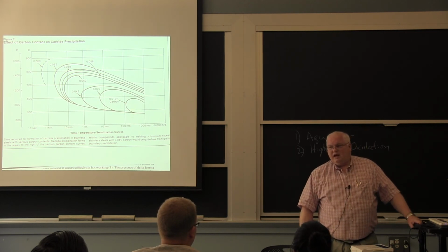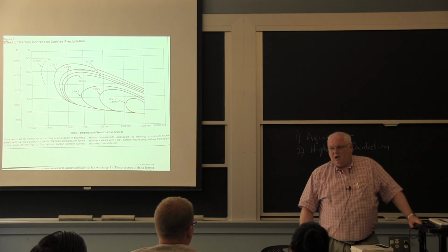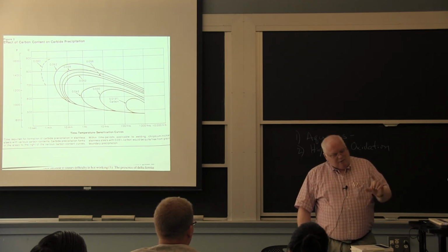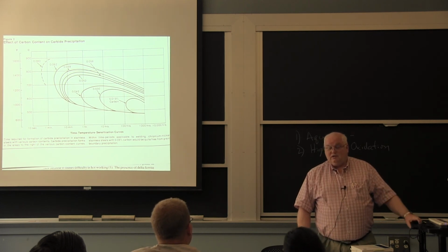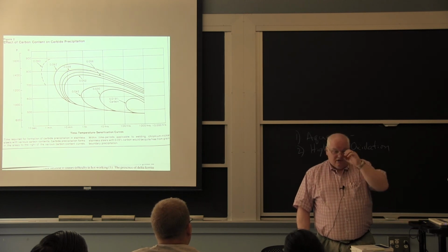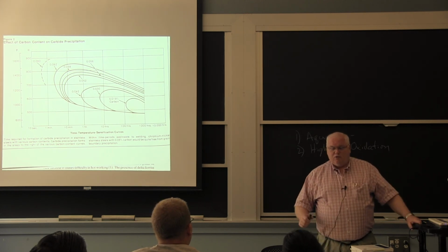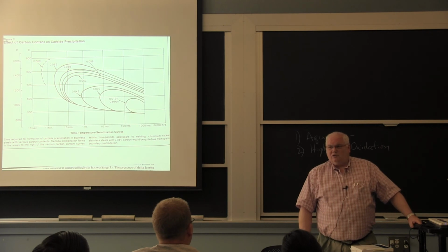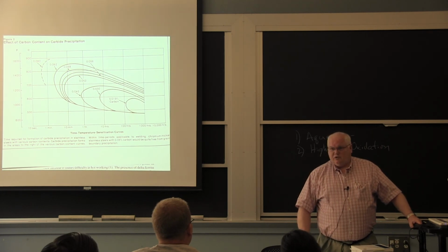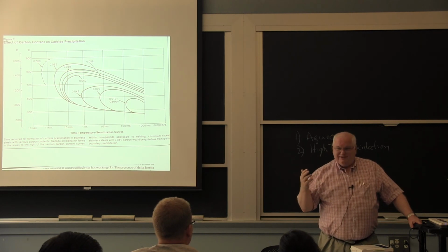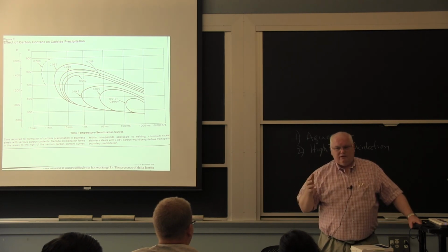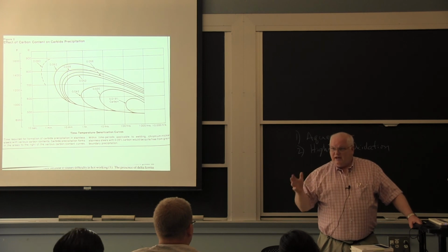water that had 1/10 of a ppm chlorine and 1 ppm oxygen. And it's the combination of oxidizing chloride environment that kills stainless steels. No one in the world thought that you could get stress corrosion cracking in 304 stainless steel at those extremely low levels of oxygen and chlorine. And in fact, except in a nuclear reactor environment, where you have high residual stresses and other things, you don't, but they did.